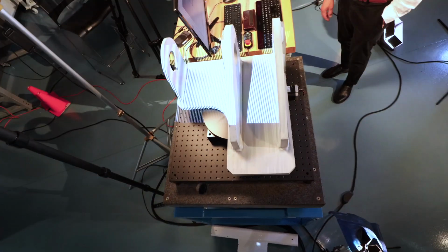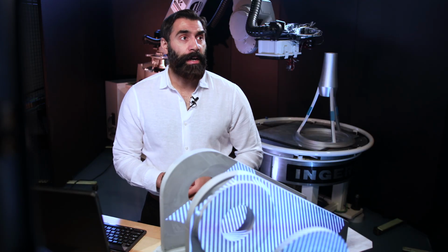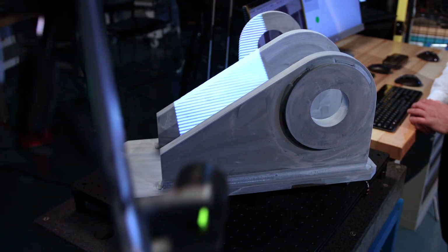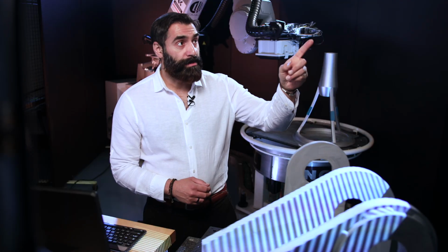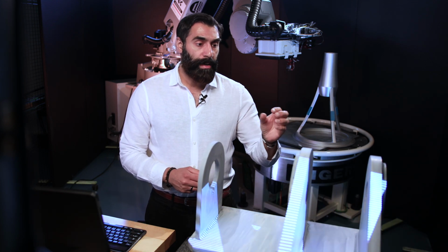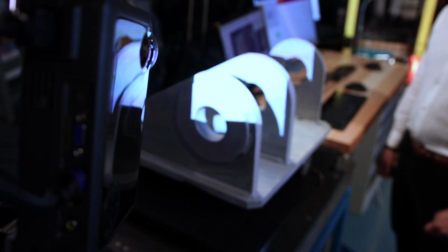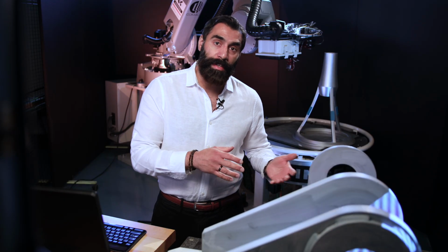The robot will move first to its first vantage point position, and it's going to start projecting a fringe pattern on the part. A fringe pattern is a known black and white stripe pattern, and that stripe pattern gets deformed as it hits the surface of the part. The camera receives that distorted pattern, and from that signal change, it's able to calculate the 3D surface information from the vantage point that it's seeing on that part. Because it's line of sight, the part surfaces have to be presented to the scanning technology so that it can capture more information on the areas that it didn't see in the previous set of scans.